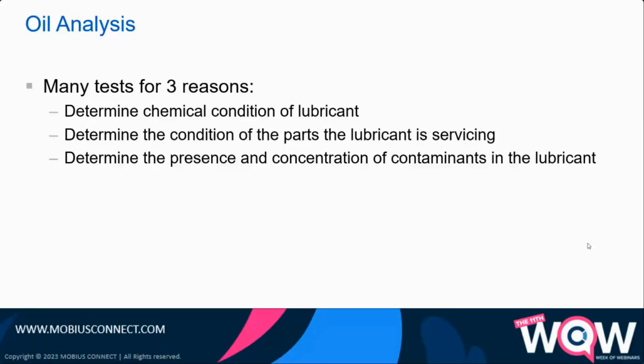And then last but not least, what people generally most highly associate with oil analysis is the presence and concentration of contaminants, right? Water, dirt, sand, fiber. Those are all contaminants in the oil that can, from a micron size, be much larger than the lubricant boundary, that film that is created in between mechanical components, and cause wear and friction, right? And cause your equipment to fail quickly at an increased rate. Next slide, please.